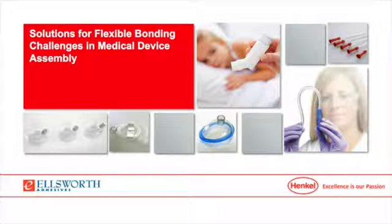We have had clients that look for a bit more information, a deeper understanding of cure, and there are analytical methods that can be used. Things like FTIR is a method that we often use to quantify degree of cure, really looking for conversion of double bonds to single bonds. But that's unfortunately not typically a method that can be employed online.